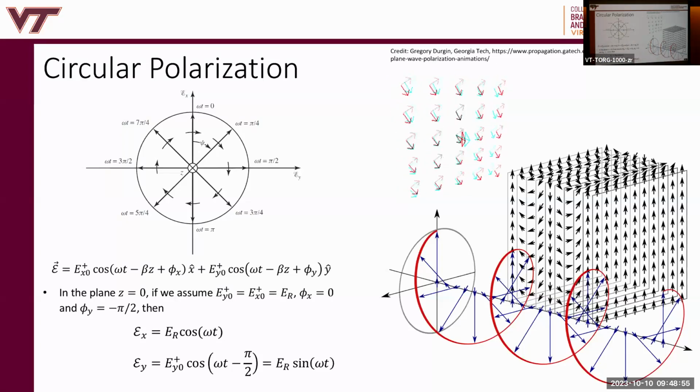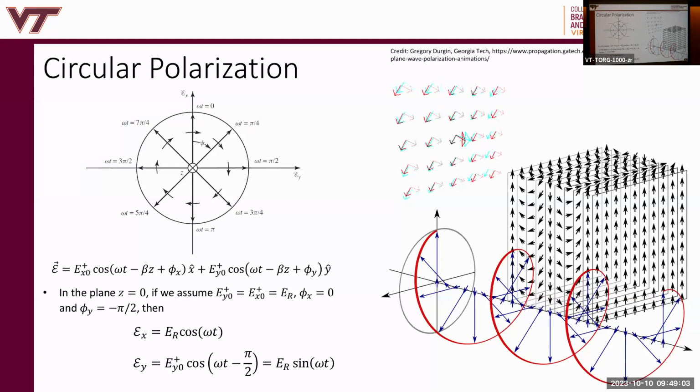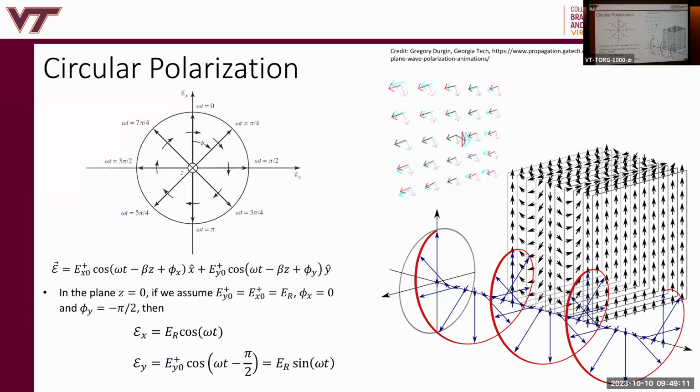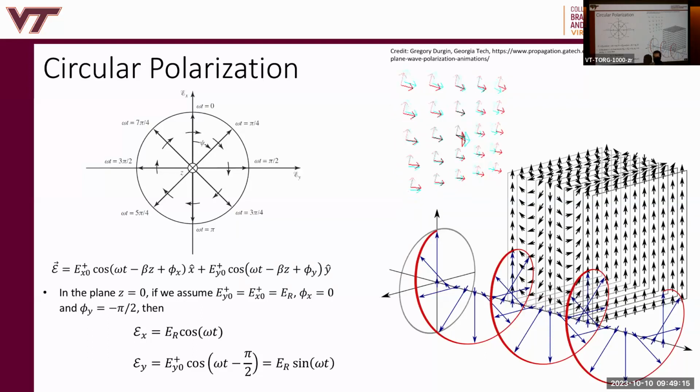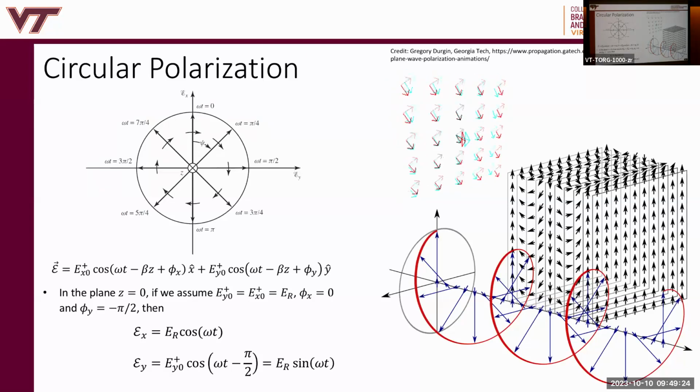All right? Yes? So if we replace pi by 2 with positive pi by 2, will it become left circular polarized? It is. Yeah, we'll see that next. Okay. So if we actually implement an antenna, in what cases do we require a right circular polarized antenna? What's the difference in implementation? Very good. So it's up to you, right? It's a design degree of freedom. RHCP and LHCP are orthogonal. So an LHCP antenna cannot communicate with an RHCP antenna, right? They're orthogonal polarizations.